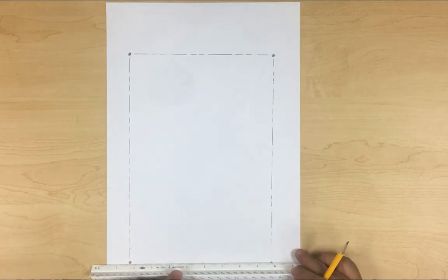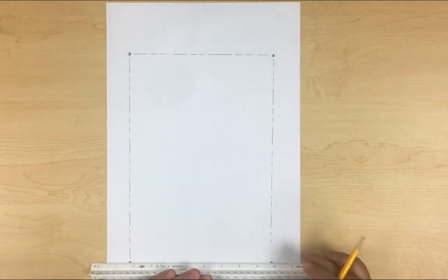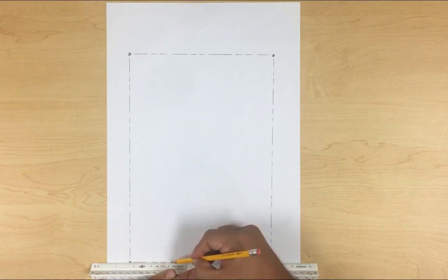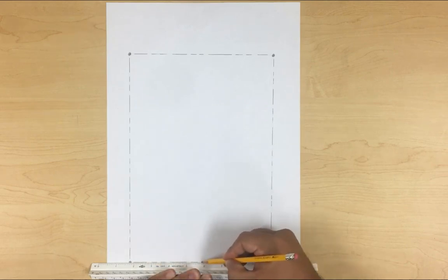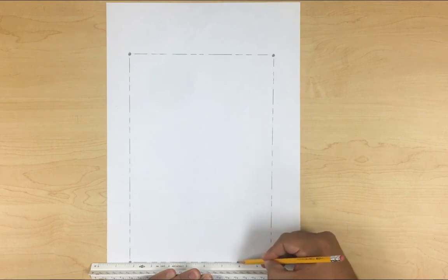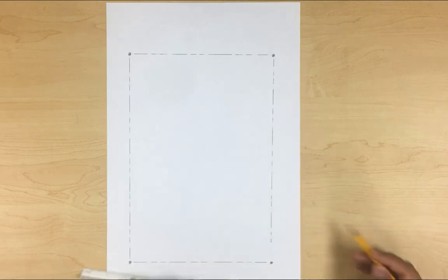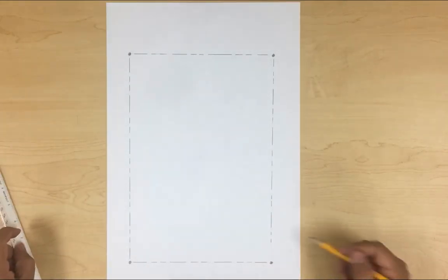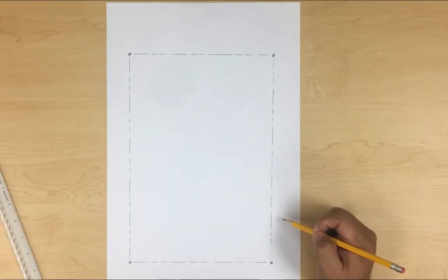So what we're doing right now is defining where our property is. That's the first thing you want to know when you're drawing your site plan or reading your site plan: where is my lot. Before you even find the structure, you want to know how big your lot is and where exactly it is located. So now we have our property line, and those should be the darkest lines you have.